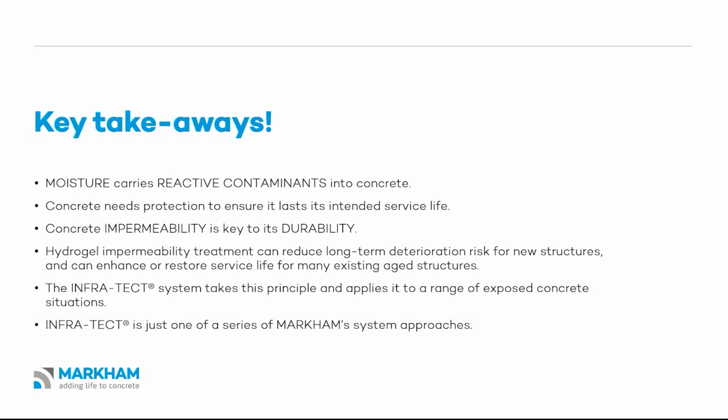So the key takeaways, write these down, take these with you: moisture carries reactive contaminants into the concrete. That's the main way concrete breaks down. Concrete needs protection to ensure it lasts its intended service life. It can't do it on its own. It's strong, it's robust, but it does have its downfalls. Concrete impermeability is the key to its durability. I think that's a really good one. That's right. Making sure nothing can get in or through will make it last a lot longer.